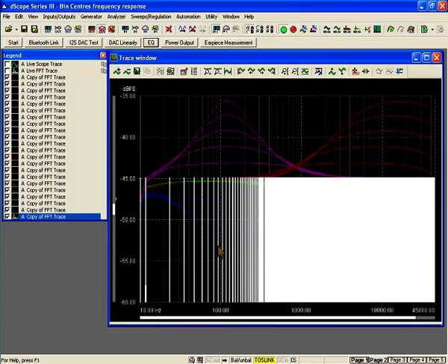On the screen at the moment, the white trace is showing you a previously measured result that I made before the session started, where I used a very large FFT size, and in doing so I've been able to expose these discrete tone components in our bin centers multitone. Let's just take a quick listen to it using the D-Scope monitor output. So it sounds almost noise-like. There are so many sinusoids in this signal that it sounds almost like noise.